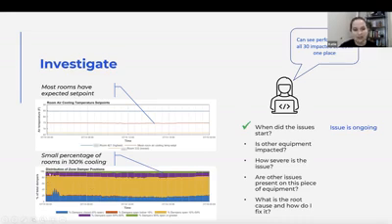So I see here this little green sliver. That is the percentage of dampers that are open at 90% or above, so that are calling for cooling. And I don't see a huge distribution there. So my conclusion to make here is that I'm not really impacting my occupants very much. I don't think I need to call the building coordinator and say, hey, we're on it. We know it's coming. I don't think the occupants quite know this is a problem yet.